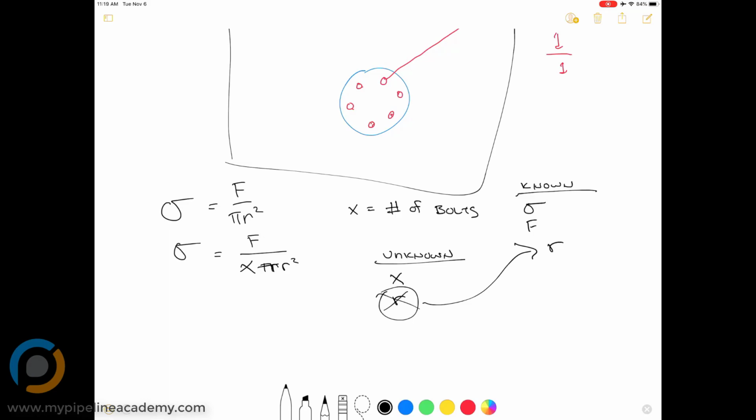How do you know sigma though? Because to know sigma, you have to know everything else. Think of it as two different sigmas. One is the sigma that you're solving for, and the other one is the yield stress. But why do we have the same variable for both of them? It depends what you're trying to solve. If you're trying to solve for that exact point at which you meet your yield strength, then by definition you're solving for that material's yield strength, and it's just material based at that point. You have to use the yield strength associated with that material.